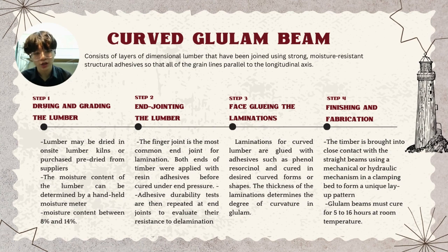The last step is finishing and fabrication. The timber is brought into close contact with the straight beams using a mechanical or hydraulic mechanism in a clamping bed to form a unique layout pattern. And remember, the glulam beams must cure for 5 to 16 hours at room temperature.